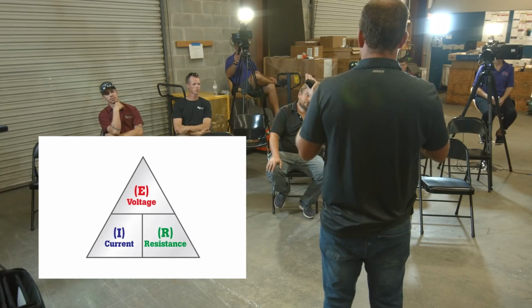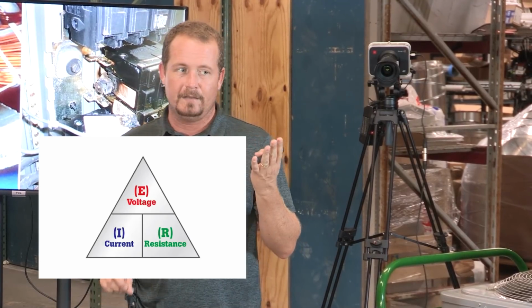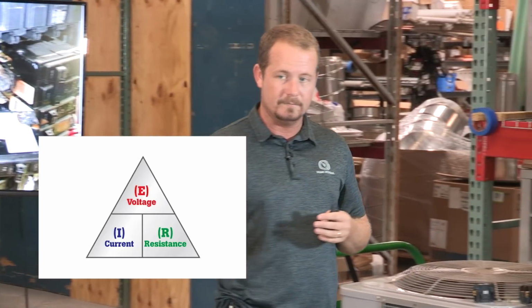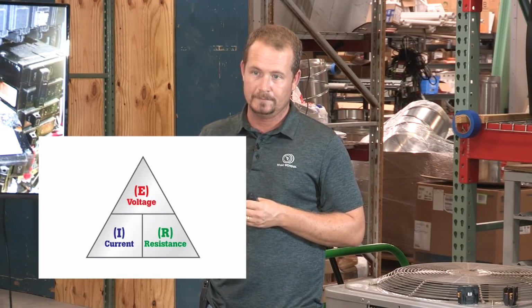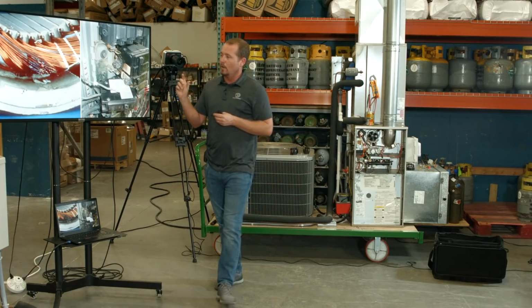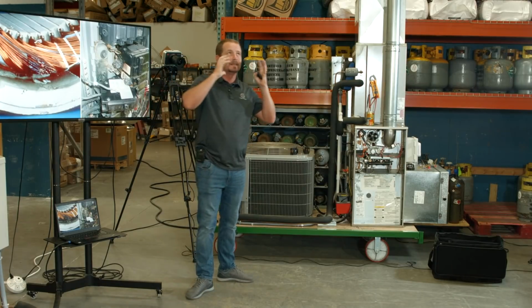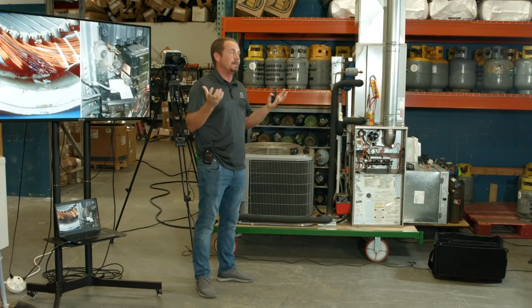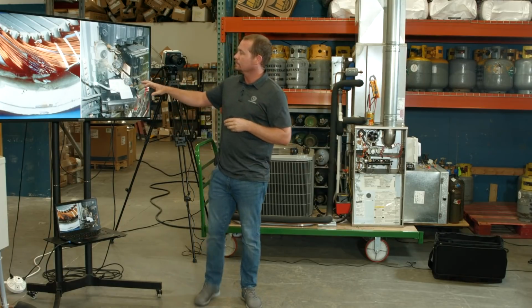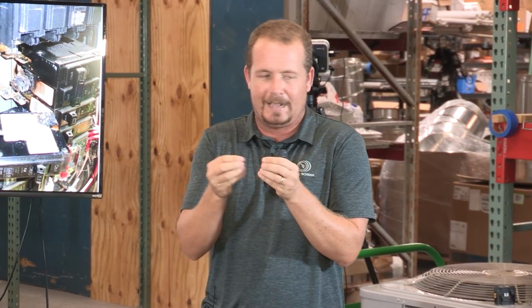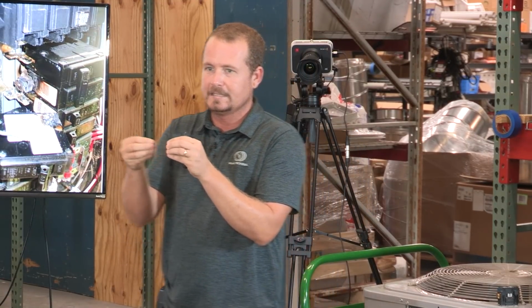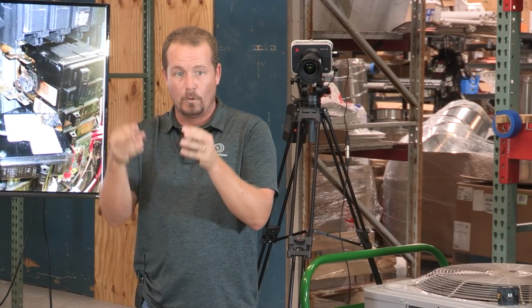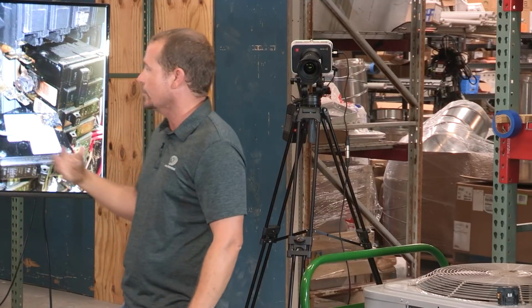Down. Goes down. That means that in your circuit, you have more or less heat overall when your current goes down. You have less overall, right? And this is why it gets kind of tricky. At the end of the day, it doesn't really matter that much. We know we need to have a good connection, but the resistance does lead to a problem. But even more than that, the lack of ampacity, amperage capacity through that connection leads to heat in that area, which then leads to more carbon, which then leads to more heat, which then leads to more resistance. So you're going to get a couple things.